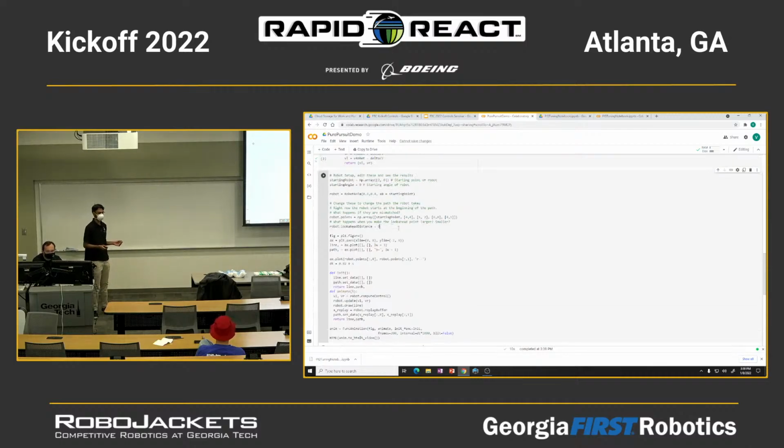distance. So what do you guys think happens if we make the look ahead distance larger? What sort of behavior do you think the robot will take? You can make it like 1.5. So what do you think it's going to do? Turning prematurely? Relative to the path, how close to the path is it going to stay? You think it's going to be farther away from the path?